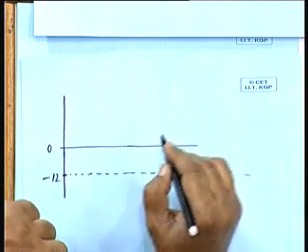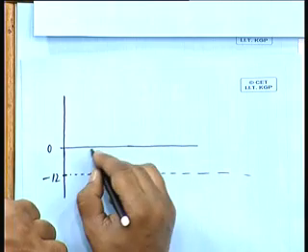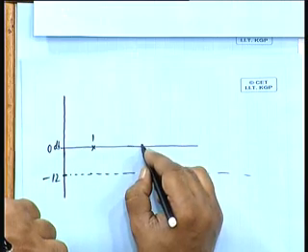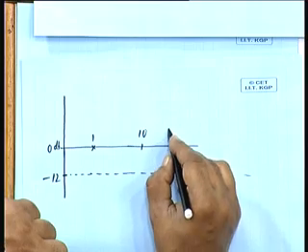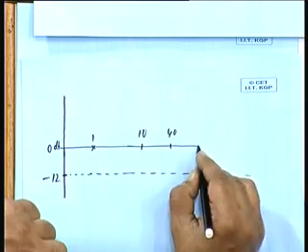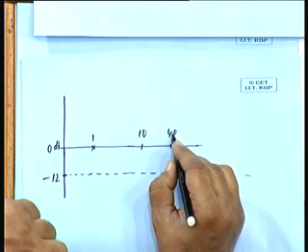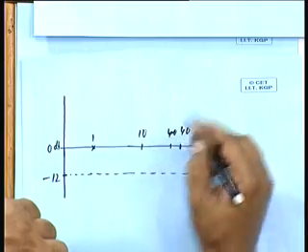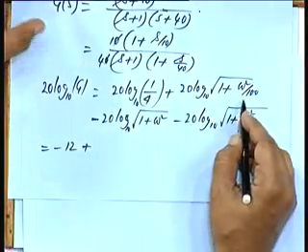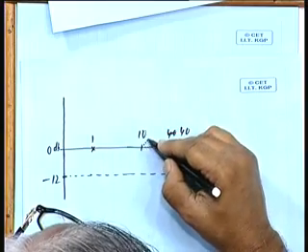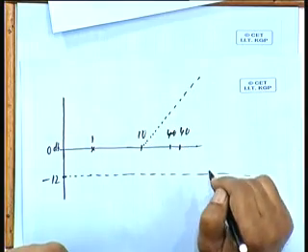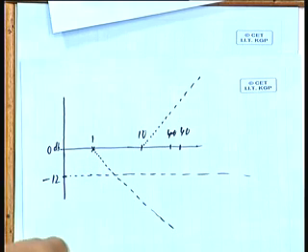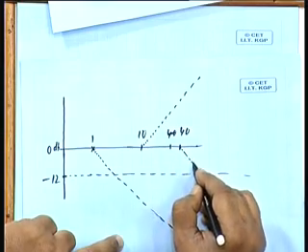The second part is at omega equal to 10. This is 0 dB, this is say 1, this is say 10, this is say 40. They are not really to the scale, 40 may be somewhere here. So, at omega equal to 10, you are having a numerator function, that means it will be increasing, 20 dB per decade line will be like this, and at omega equal to 1 it is falling like this, 20 dB per decade. At 40 again it is falling like this.